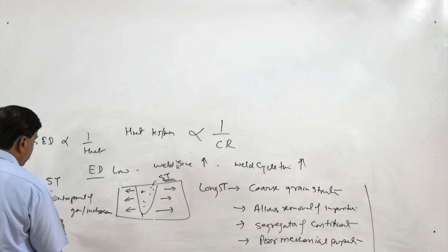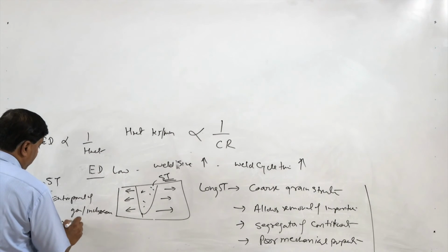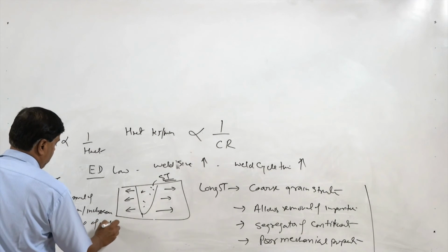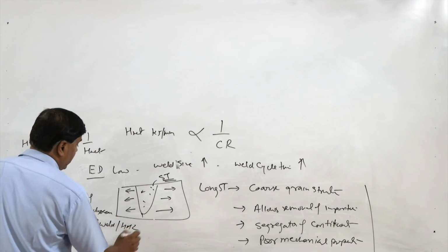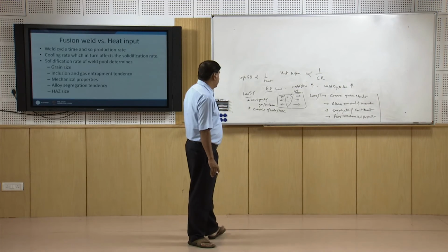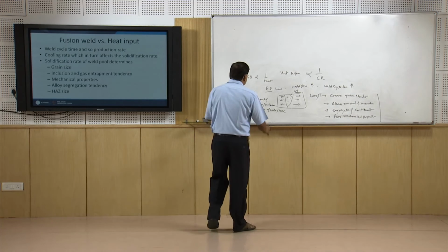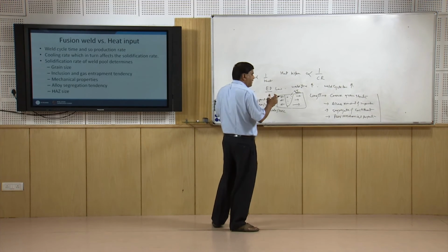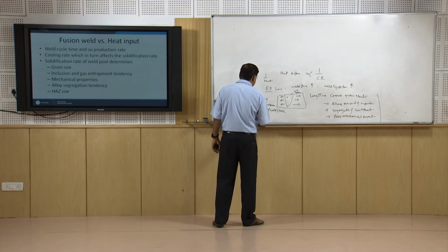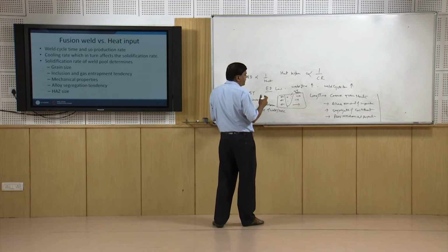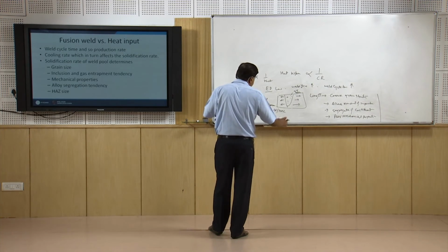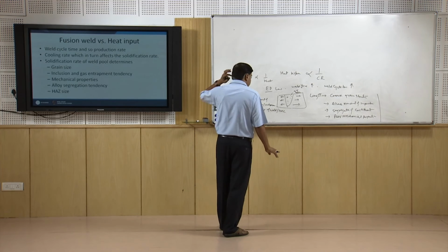This is one thing, and it can lead to the cracking of weld and HAZ, especially in the case of hardenable steels. So sometimes preheating is intentionally done, so that the cooling rate can be reduced and the solidification time can be increased. So these are the different aspects related with the